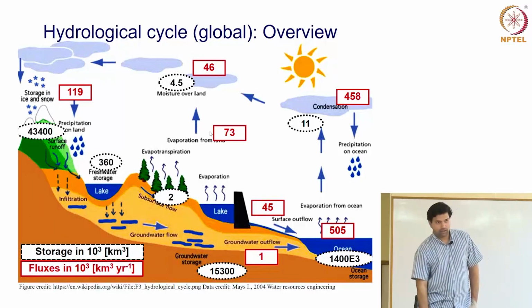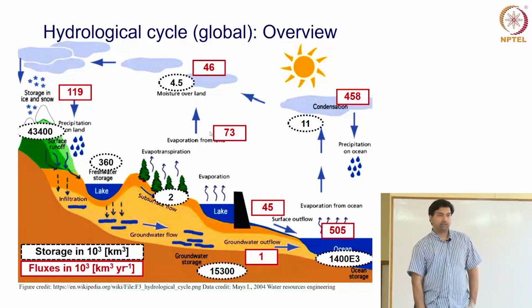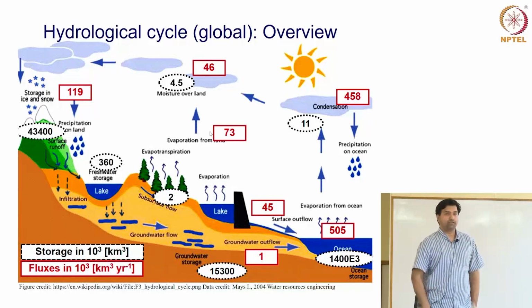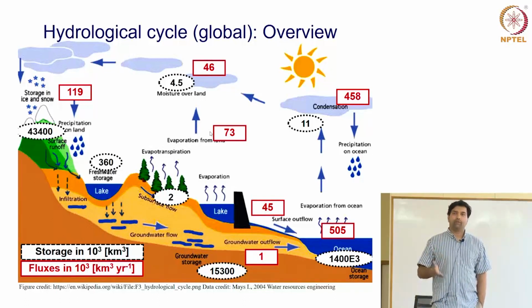When you think about storing water on the surface versus storing water in the ground, think about which water is more accessible or more easily retrievable. If you store it in the ground, it's not moving very far away, and it's there for a long time. You're not occupying additional space on the surface. You're preventing evaporation, and water moves fairly slowly in the subsurface. So there are advantages to recharging groundwater.